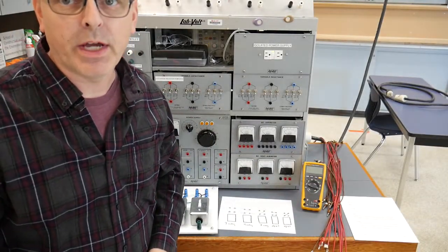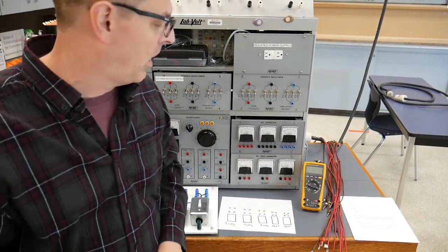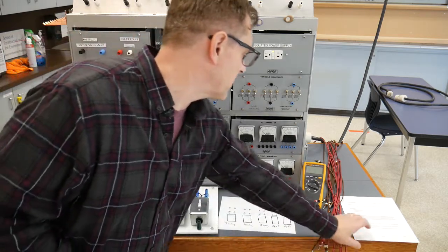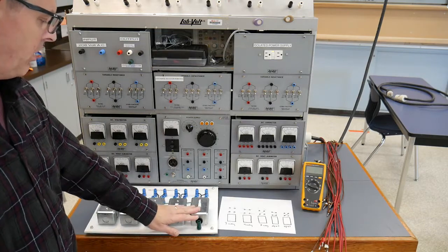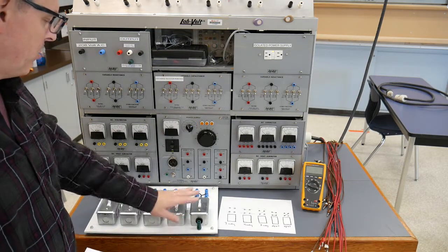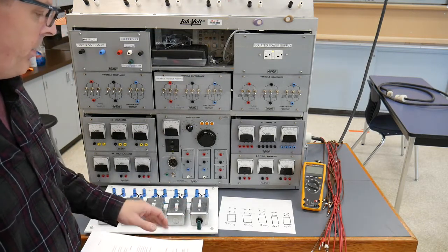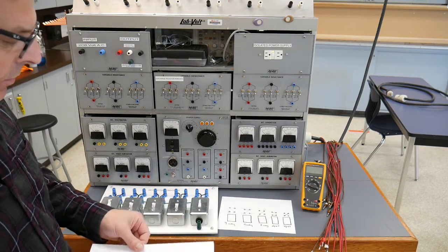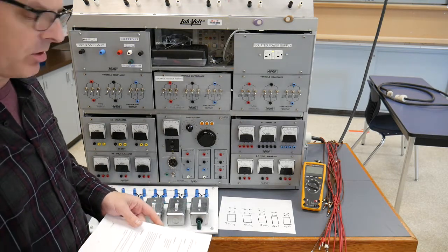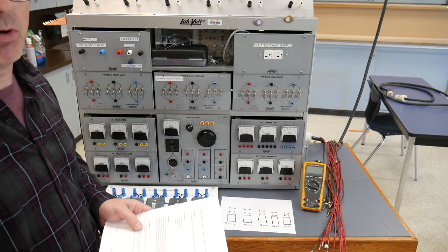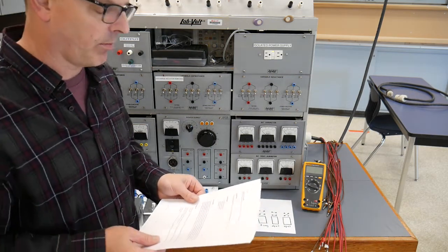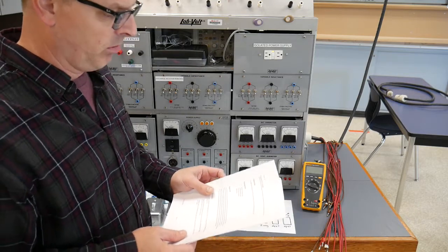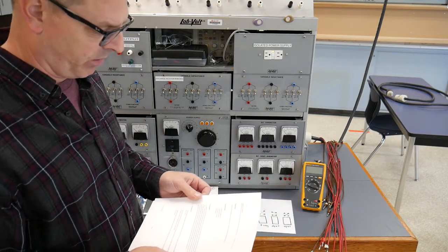Hello. Okay, so this is now lab 1-6, switching circuits. In this lab, we're going to look at the board that we just metered out to make sure which devices were what. We are then going to connect them up to the 4 different types of circuits they're going to ask us to do. They're going to ask us to connect up a single pole, single throw switch, a double pole, double throw switch, or double pole, single throw switch, a 3-way circuit, and a 4-way circuit.